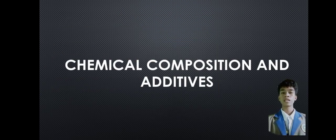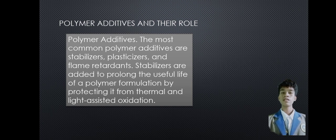Chemical composition and additives. Number one, polymer additives and their role. The most common polymer additives are stabilizers, plasticizers, and flame retardants. Stabilizers are added to prolong the useful life of a polymer formulation by protecting it from thermal and light-assisted oxidation.